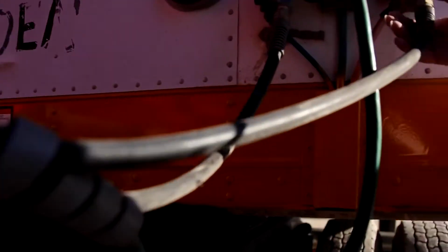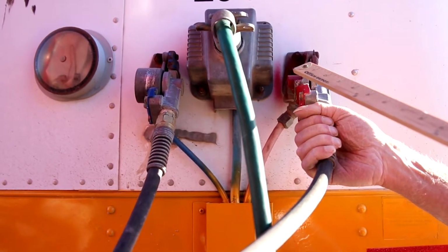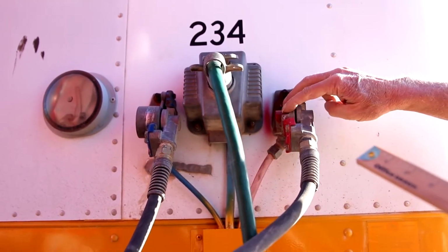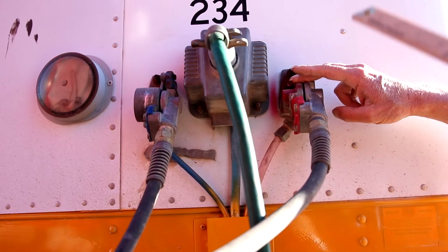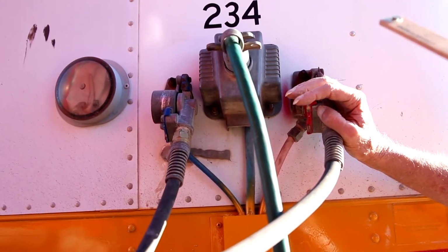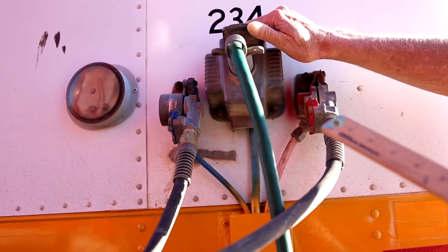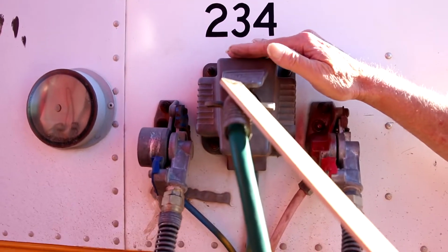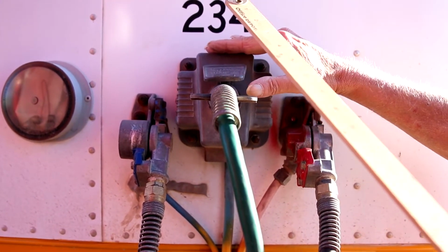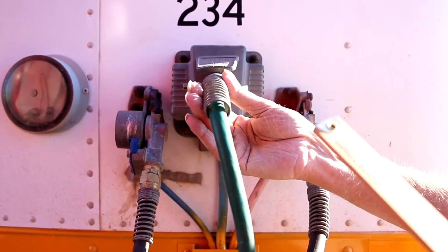Continuing on back. My air lines, my primary and secondary air lines, are attached to my trailer by a set of glad hands, these large metal pieces here. They're not damaged or broken. And on the inside of those, they have what they call a glad hand gasket. It's a rubber piece. No audible leaks. Next is my electrical line, or some people call it a pigtail. It is attached to the trailer with a safety catch also. And again, no exposed wires.